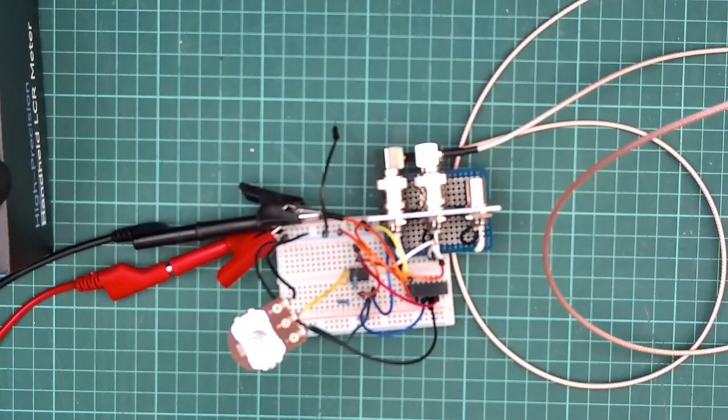So I'm powering the circuit at the moment just from a power supply, 12 volts DC, and we're drawing 0.024 of an amp. So, as I say, low power, and we are actually using the little all-in-one power supply chip to provide the voltages onto the circuit. So I think that'll be absolutely fine.